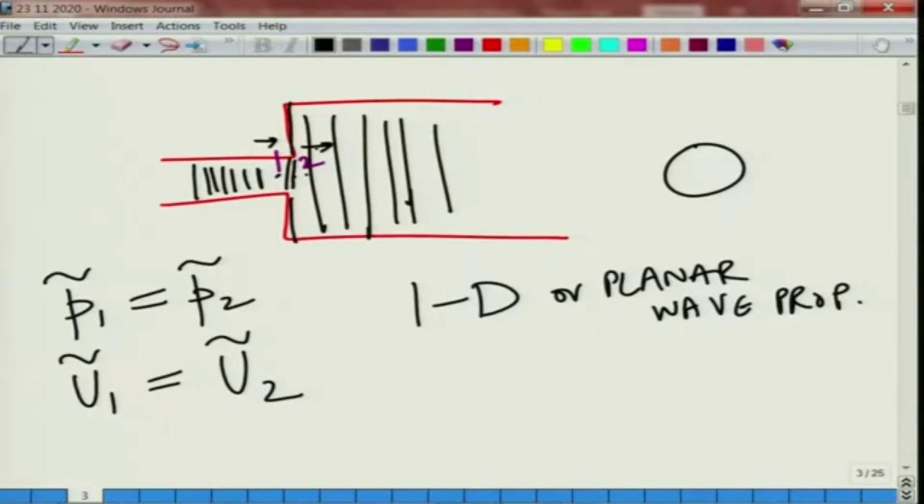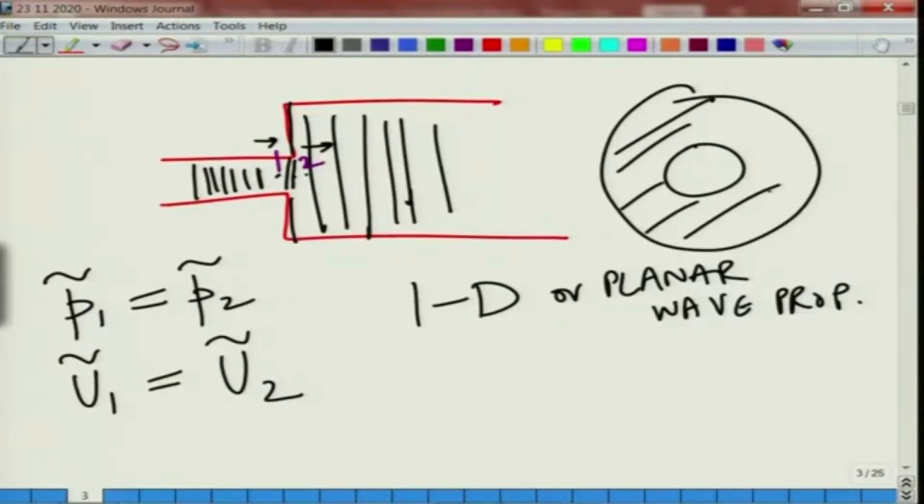Now, as we were discussing previously, the annular surface area is assumed to be rigid, that is to say, it is a rigid walled annular surface. So, normal velocity is 0. So, you have un equal to 0 here, with normal velocity over the annular area being 0, because the end plates of the chamber are not vibrating, they just remain stationary.